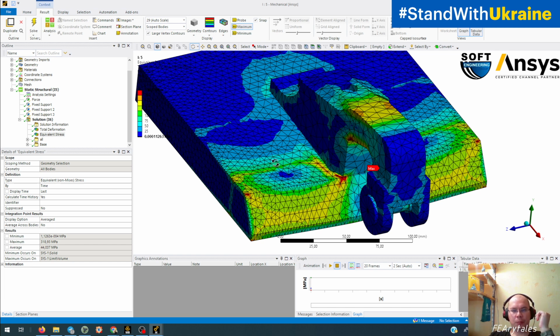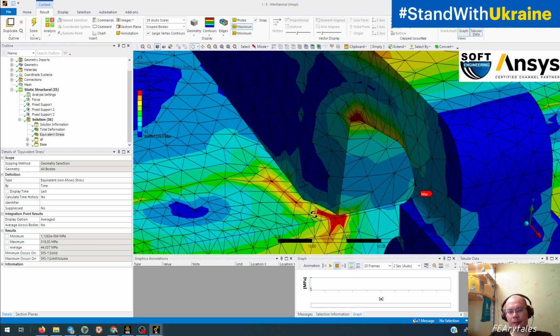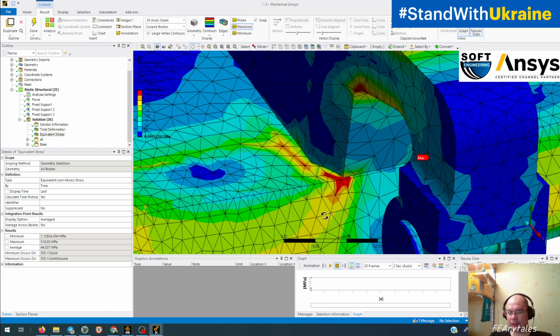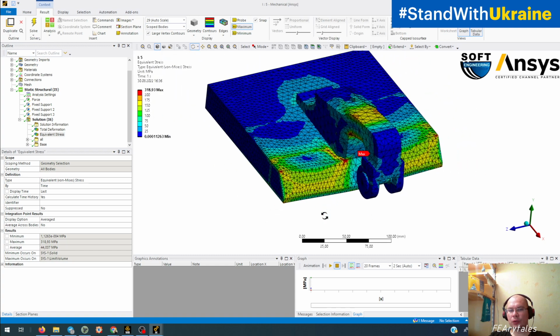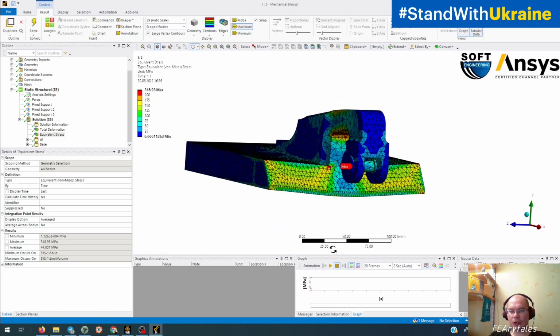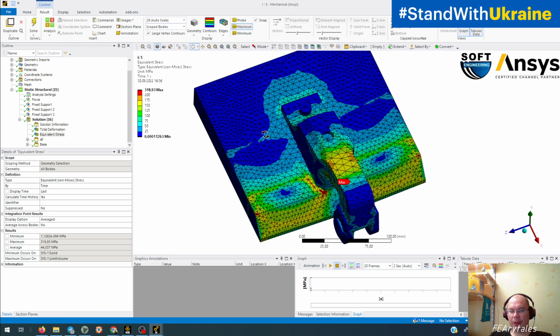It depends on many reasons. It depends on bonded contact between those two parts. It depends on position of elements and nodes. It depends on many different types of tasks. And also you might understand that this construction has several places with hotspot stresses, with local stresses that would be very big or infinite.